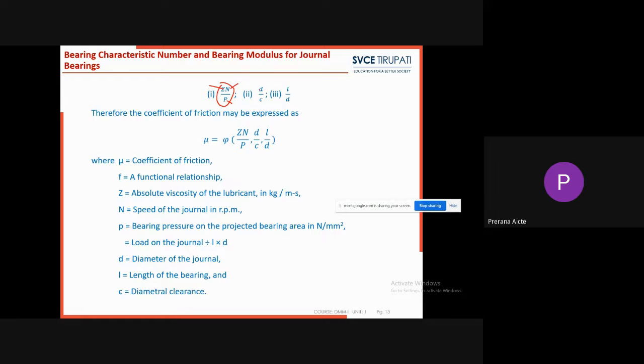So this entire formula we call the bearing number. The second one is the diameter to clearance ratio. See here, this one is a journal bearing, and this one is the journal. This is the diameter of the journal, D. C means clearance, the gap between the journal and the bearing. That is called the diameter to clearance ratio. This D by C value you can take from a table for the application. If it is a steam engine, the C by D value is nearly 0.002, like that. In the table the C by D value is given; we take the reciprocal, then you get the D by C value. So based on the application, we take the value from the table.